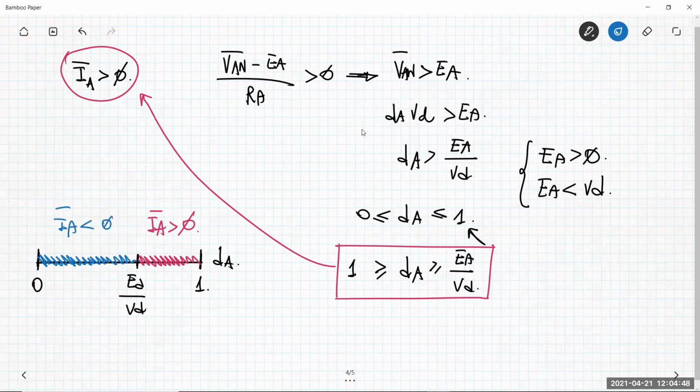So this circuit has an intrinsic bidirectionality for the current. This is why it is called a bidirectional converter, because you can play with the unitary switching function, providing a specific duty cycle, DA, commanding the position of the switch. And according to what I'm saying here, you can have a positive or negative current flowing into the motors. So this is something that is bidirectional in current.